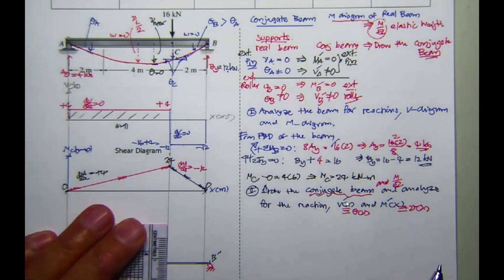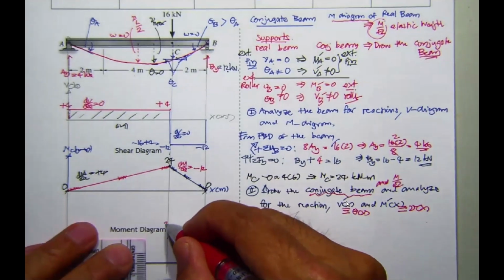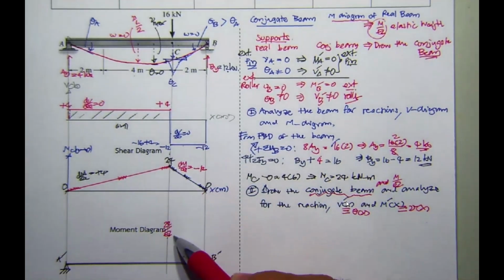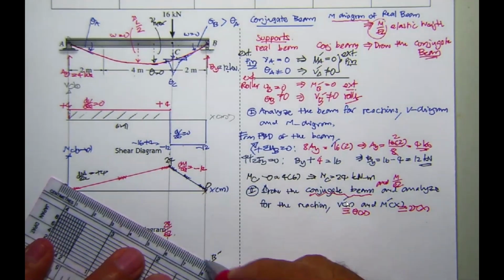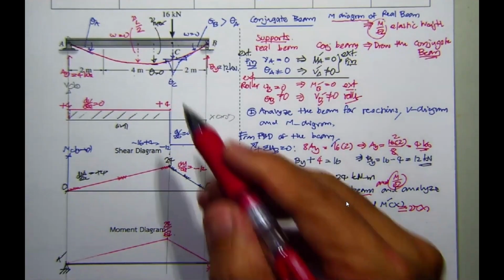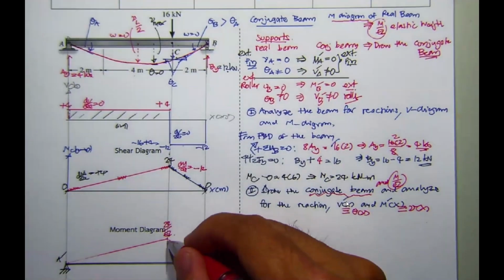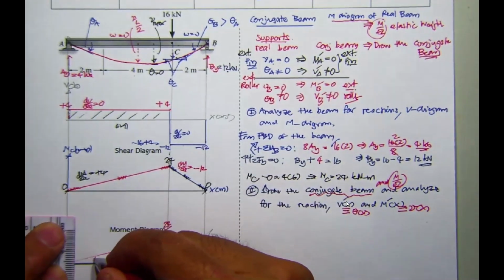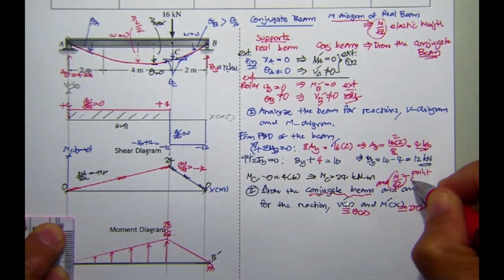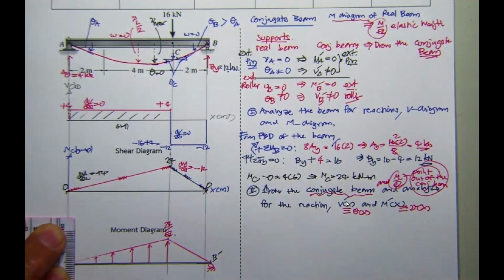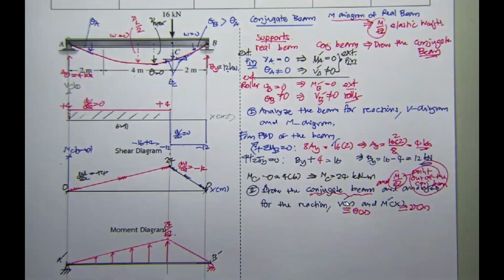By putting this one, this is going to be 24, but it's going to be 24 divided by EI. Okay, it's going to be the moment divided by flexural rigidity, and then you just draw the same picture over here, and then you can determine the direction of M over EI. I said the downward is positive, so this is going to be upward. I should say the M over EI always points out of the conjugate beam. This is important. Always point out. If it's negative, it points downward. If it's positive, it points upward. Now you are ready to analyze the conjugate beam.